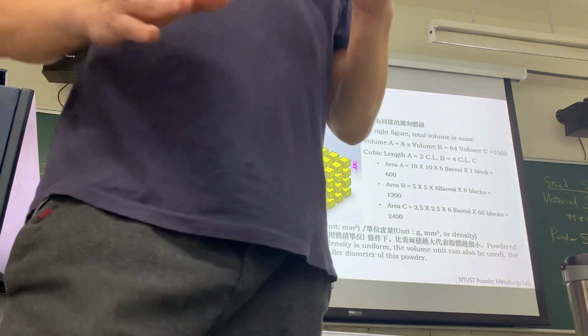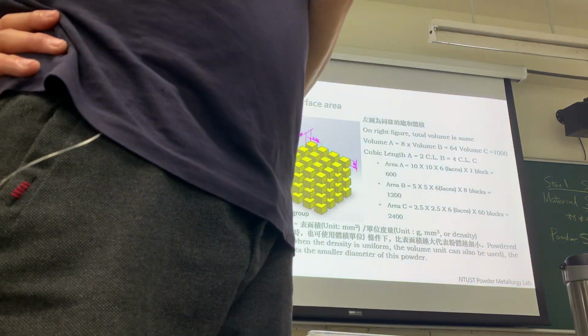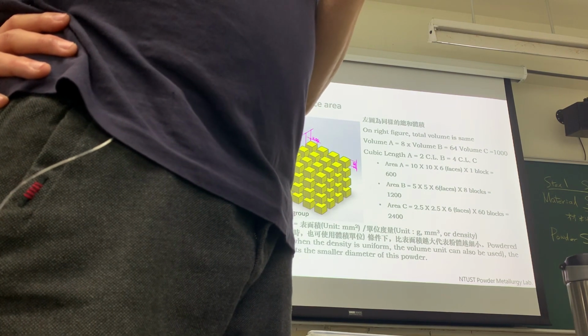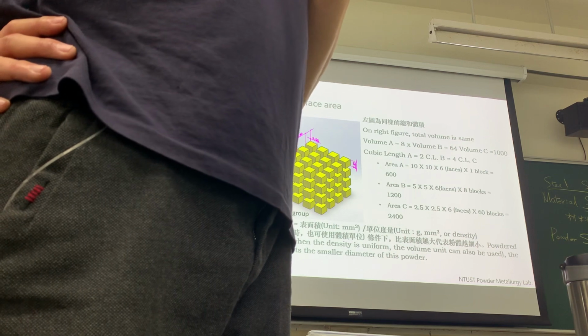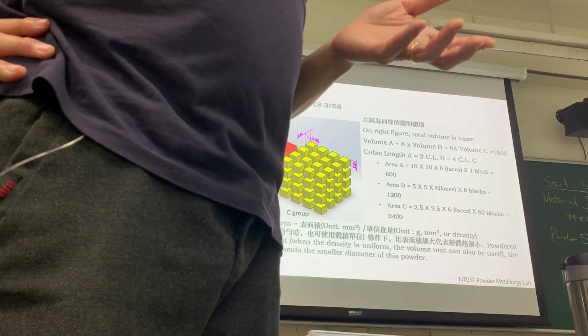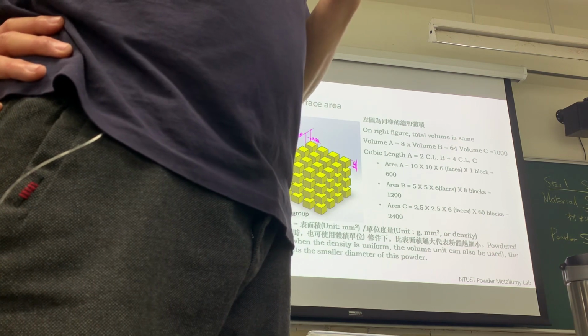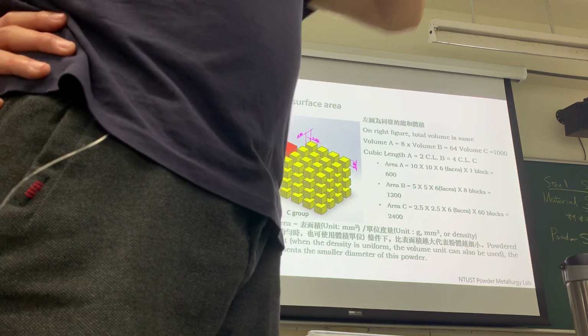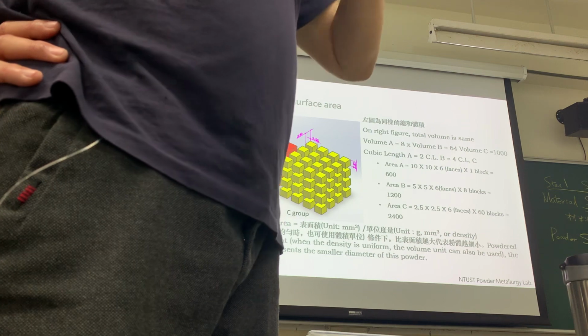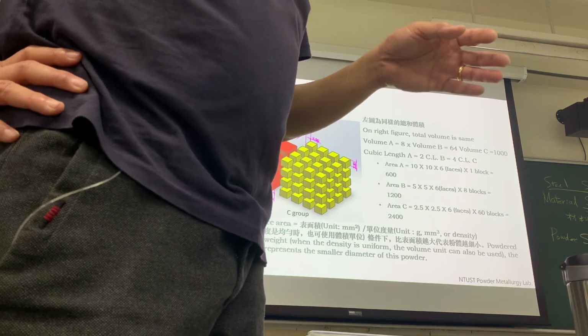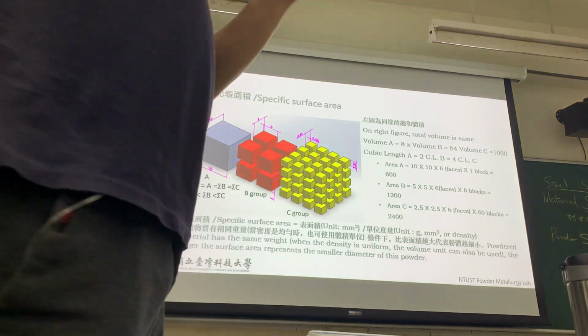Just remember, in MIM we just use powders below 13 micron. Small powder may not be good, but when the powder size is small, your surface condition will be good, smoother after sintering. But your process will not be easy to control. So just remember this one.